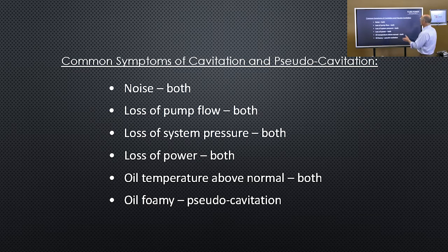All right. So common symptoms of cavitation in a hydraulic system are, and these are both cavitation and pseudocavitation. Just so we understand each other, pseudocavitation is air contamination of the oil. In other words, I'm not starving the pump for oil as in cavitation.